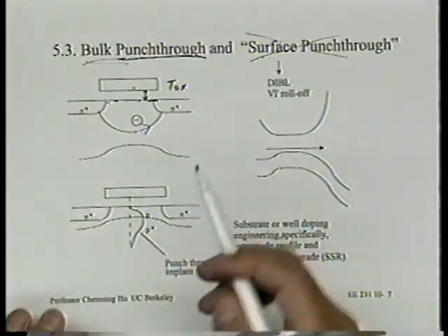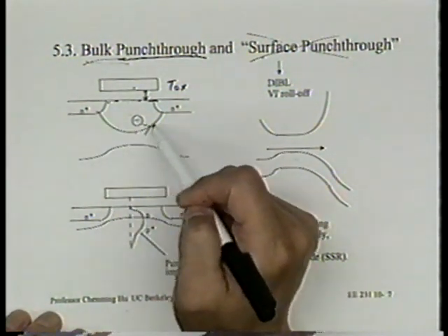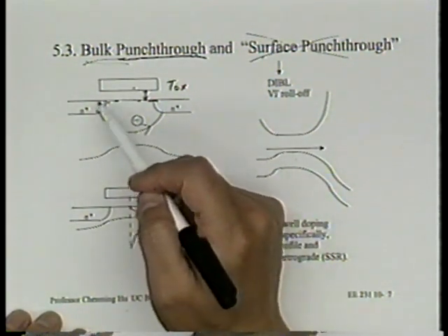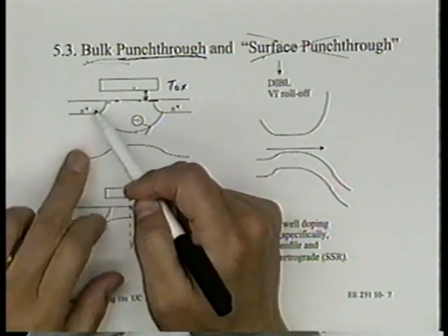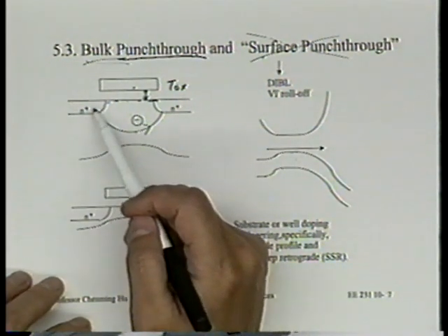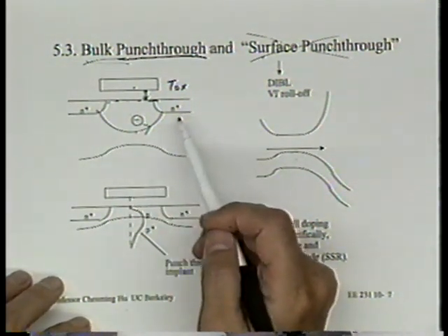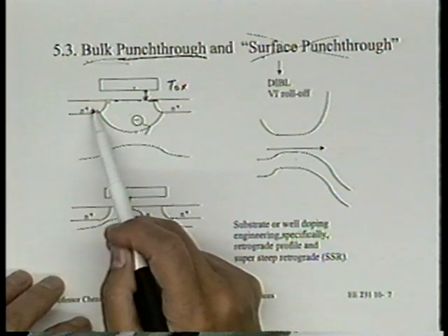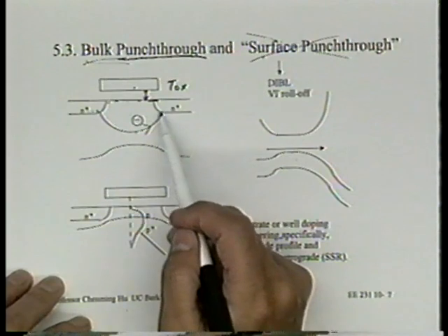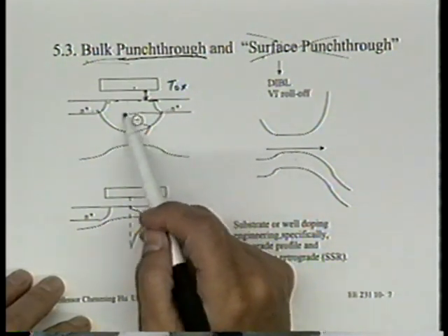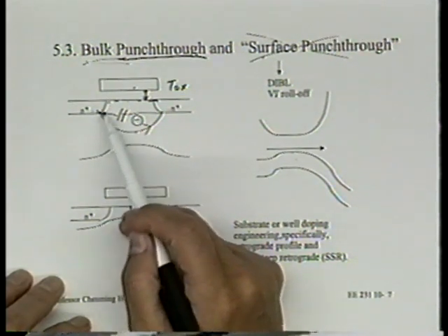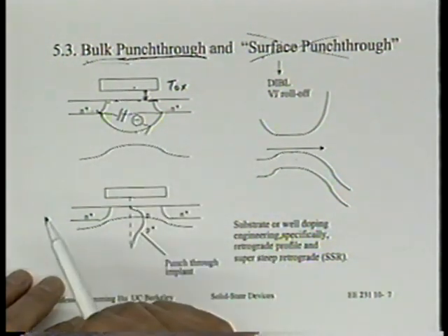So if you draw the energy band diagram along this profile, for example, along this trajectory, we usually don't draw an energy band diagram along a curved line, of course. But if you did that, you draw the energy band diagram along here, right? We had a good P to N-plus barrier, that built-in potential before. But just because of the capacitance at this point to the drain, nothing's preventing this from being pulled down, because it's too far from the gate.